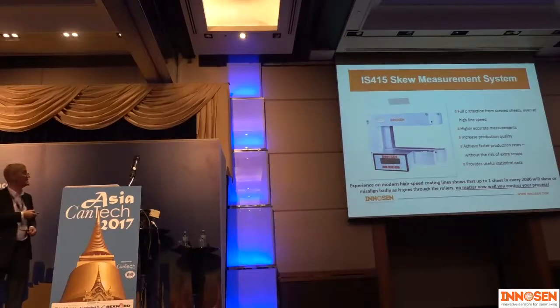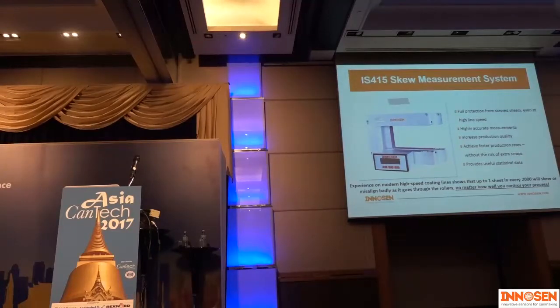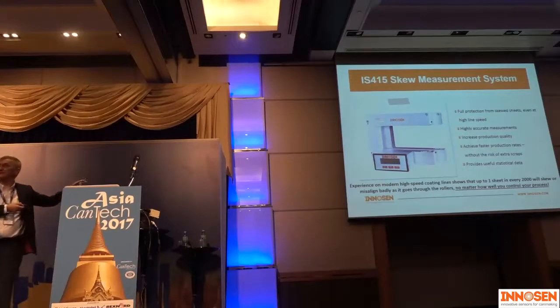It makes a standard deviation and an average. For example, if you normally have a standard deviation of 0.2 and you see it creeping up, it could be that the tension on your chains is insufficient, that your dogs are worn out, or that there's something wrong with your gripper cylinder. That is the kind of information you will get from this system.